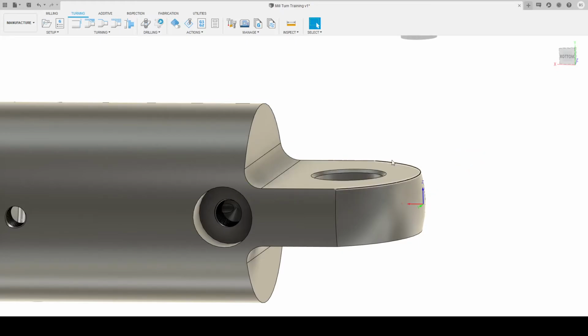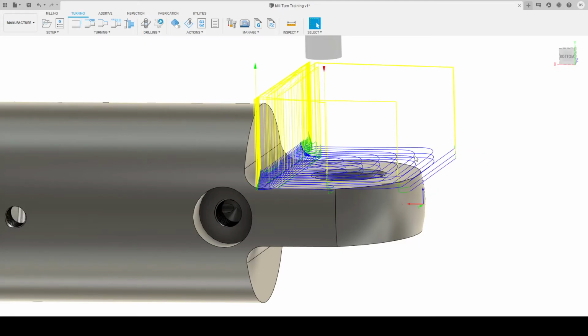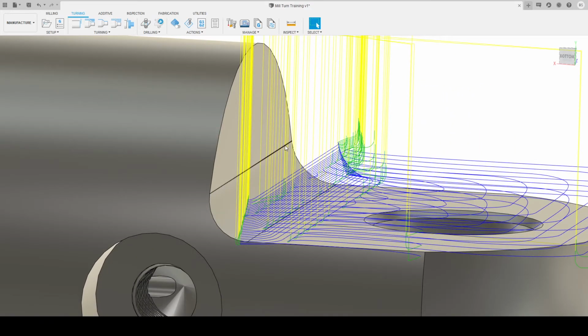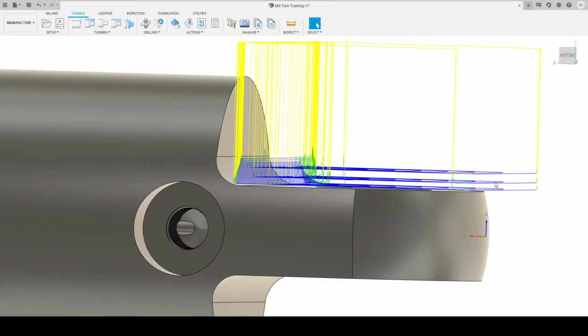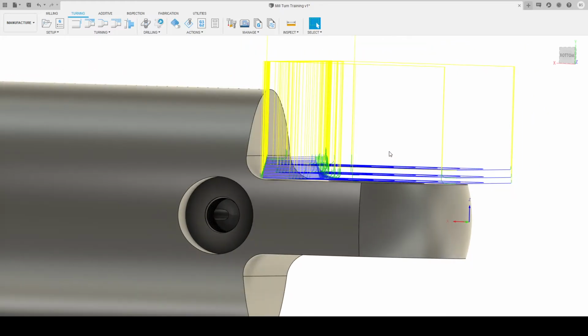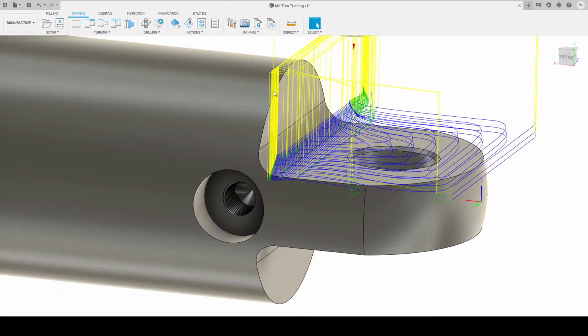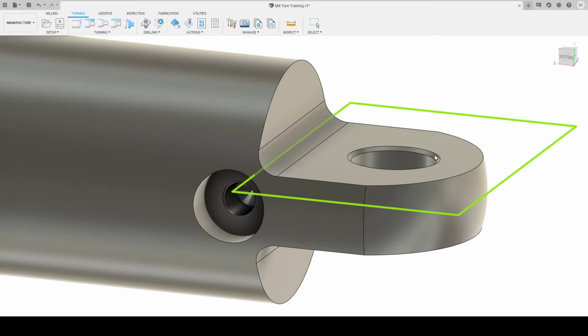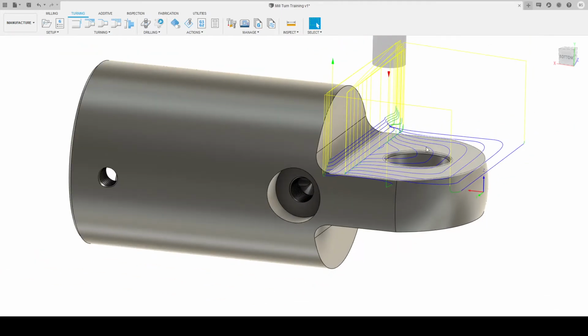We'll go 2 mil. So now it'll go 2 mil step downs, and remember we're looking from this point to this point, so it's got three step downs if we do it that way, which is fine. So these tools can typically go 25 mil step down, and we will go 1 mil. That's red because we have defined the tool flute length as 20 mil when we modeled the tool, so we'll just go 20 mil. Alright, that looks good. So we'll clean up this floor now.